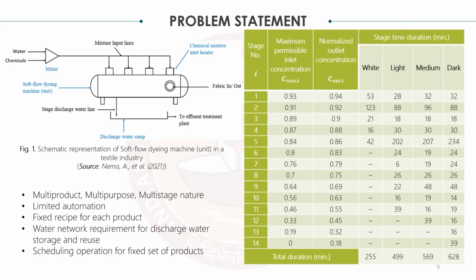So that should tell you freshwater requirement may not be very important at the earlier stages, because the concentration allowed is large, but you will require fresh water at the later stages, especially in the last stages. You have no possibility of recycle at the last stage, but at the beginning stages you could actually recycle things. That's what we are looking at.